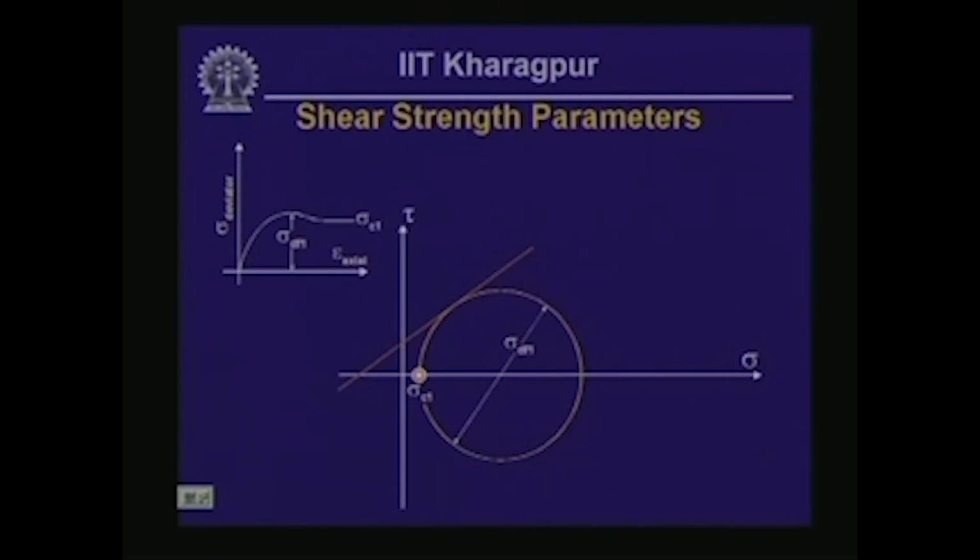If you recall, the first test of the series of triaxial tests was conducted at the smallest value of cell pressure, and the deviatoric data obtained from the triaxial test are presented on the plot near the top left of this slide.